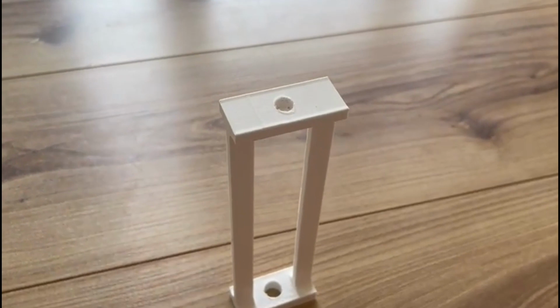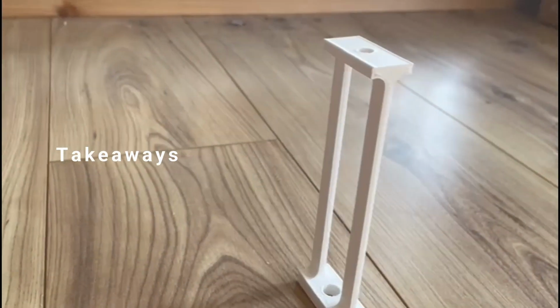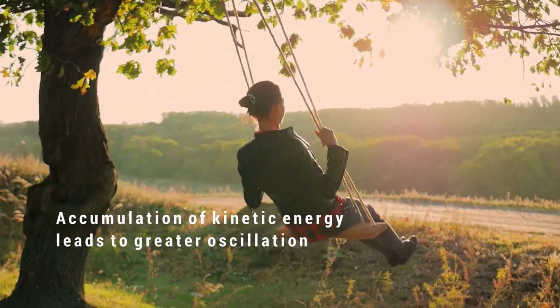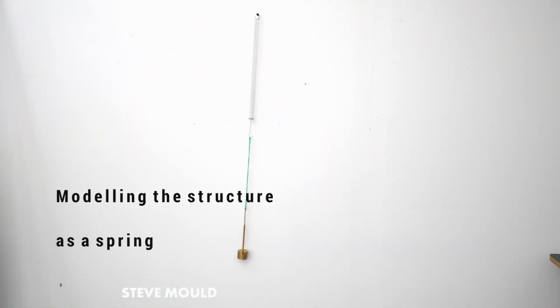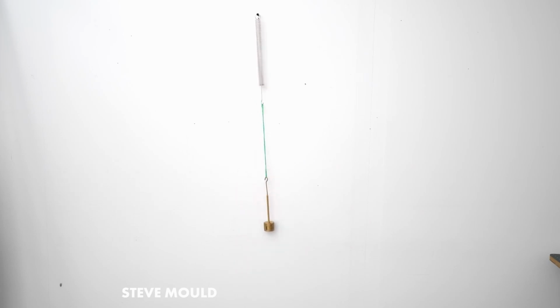So with a mass of 16 grams and a natural period, we learned that elastic structures accumulate kinetic energy leading to higher magnitudes of oscillation than we would have predicted. So instead of modeling a static structure, the structure should have been modeled as a spring, and the peak displacement should have been calculated by accumulating the energy provided by the earthquake with some realistic factor of decay. Once absorbed energy is known, we can obtain the displacement using Hooke's law.